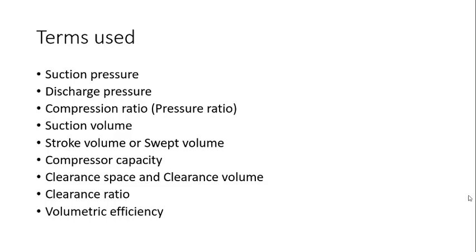The next one is clearance ratio. It is the ratio of clearance volume to the swept volume, which is called clearance ratio. And volumetric efficiency is the ratio of stroke suction volume to the stroke volume or swept volume of the cylinder.